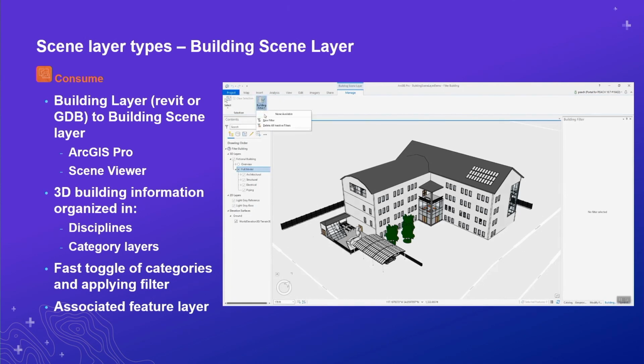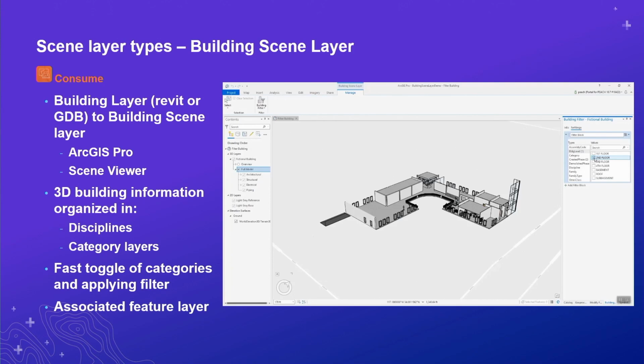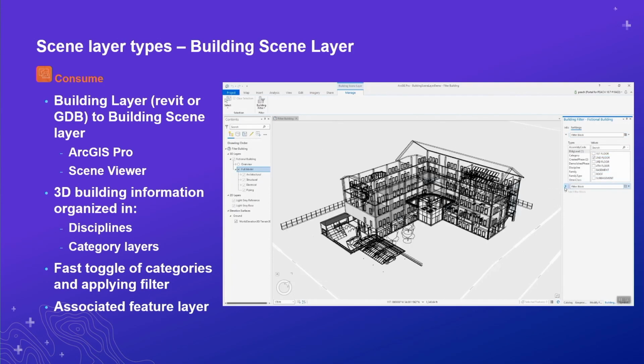I have here a fictional building, and I'm creating a filter that would only show the second floor and the outer walls as reference where the second floor in this building is. So I select the full model and I create a filter. I set a filter block with the solid mode and select the second floor, and immediately I can see all the assets of the second floor across my category layer.